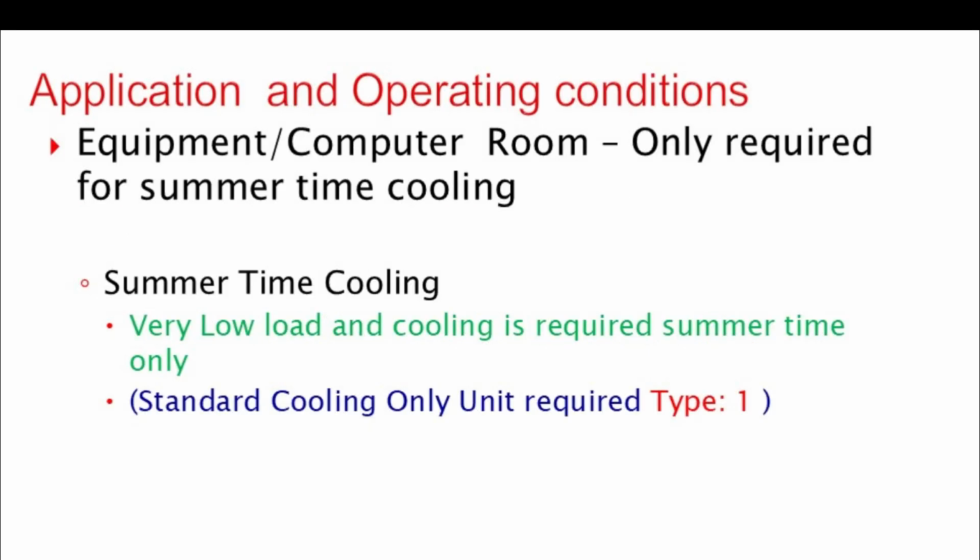The next application is similar equipment or computer rooms, but you only need cooling during summer. In this case, you can go with a standard cooling-only unit. As I mentioned earlier, this is a Type 1 indoor unit, and windscreens or low ambient controls are not required.